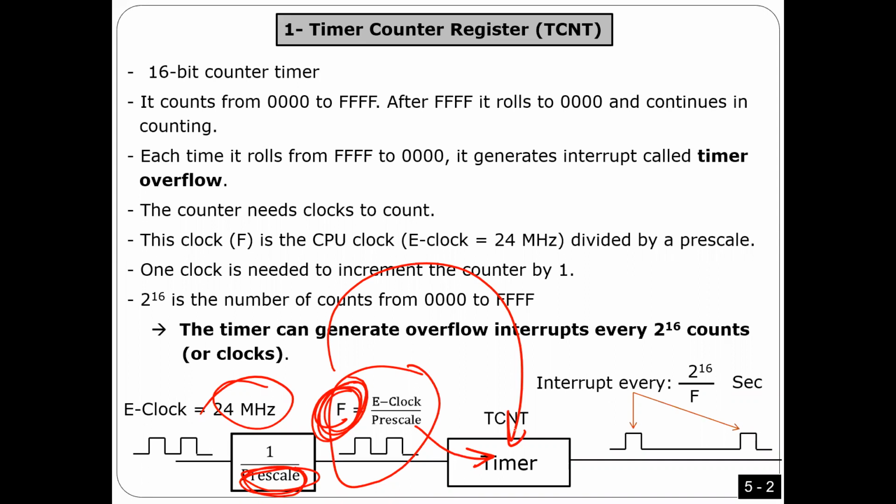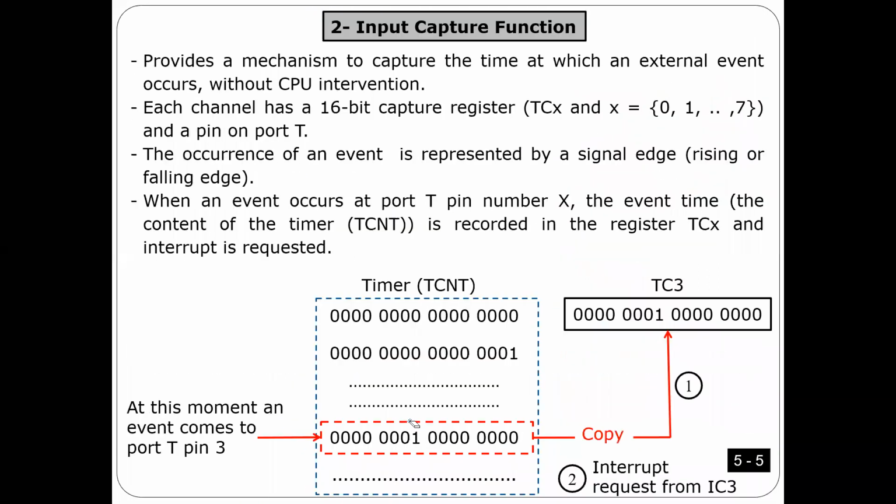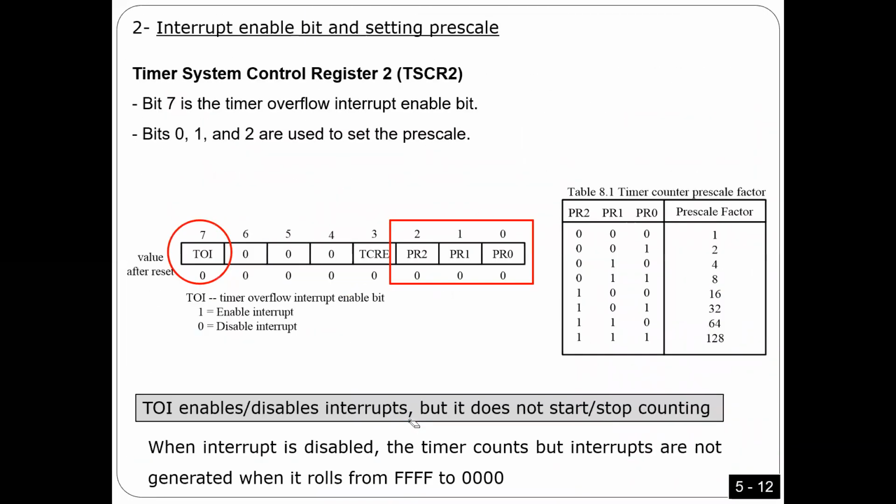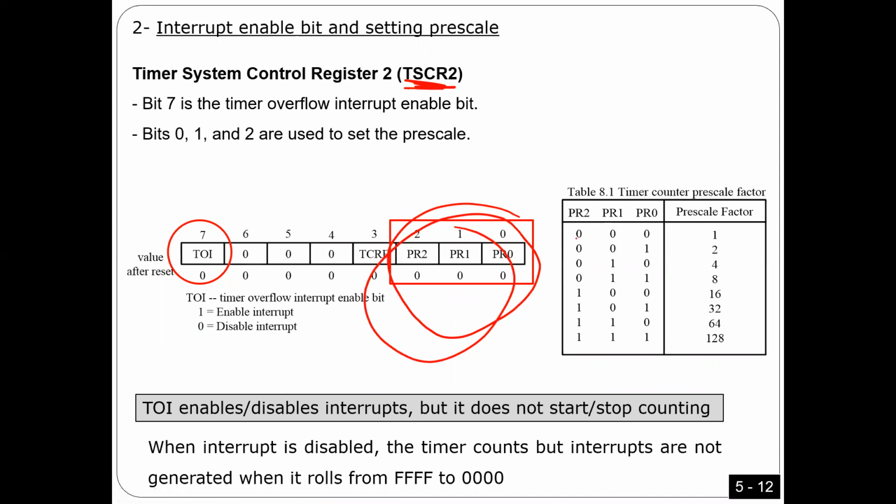Okay. So how can you control the prescaler, guys? I can control the prescaler easily, as I'm going to explain later. I just want to show what I mean. Yes, we have a register, this register, right? We have 3 bits for the prescaler here. So if you put 000 here, the prescaler is 1. That means it's going to be 24 megahertz divided by 1. So this is the fastest speed, right?